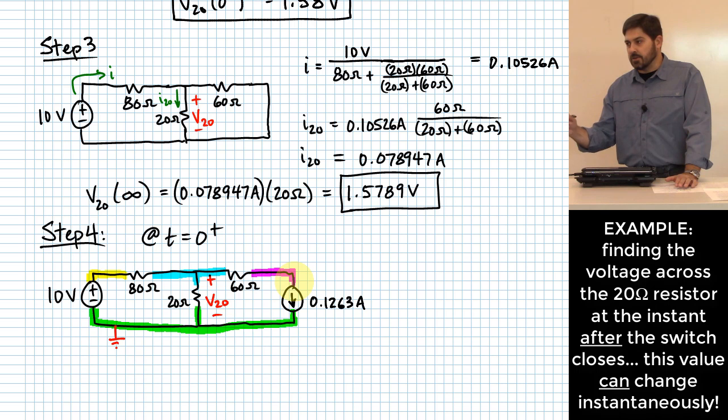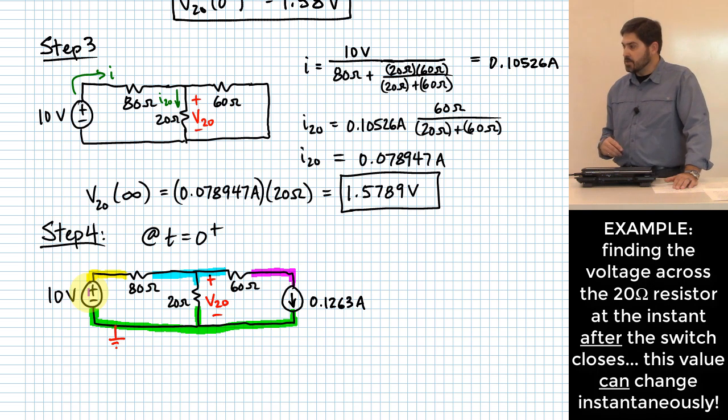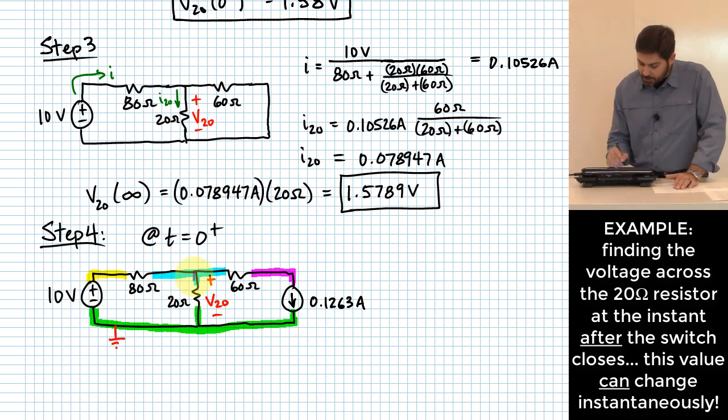Okay. Supernodes happen across voltage sources, right? So what I would say is that we actually have a voltage source connected to the ground node here. So that means we're going to treat all of that as one big super ground node, right? The next node that I would want to write some equations for might be the one up there that I colored blue. Let me write some variables as well, because I didn't do that part yet. Let me call this V1, V2, V3.